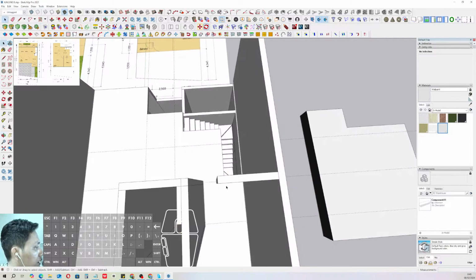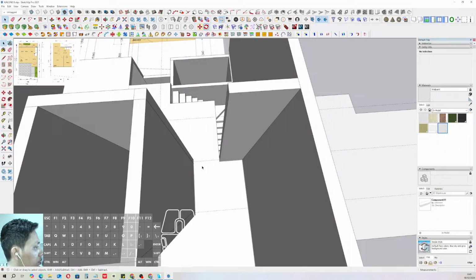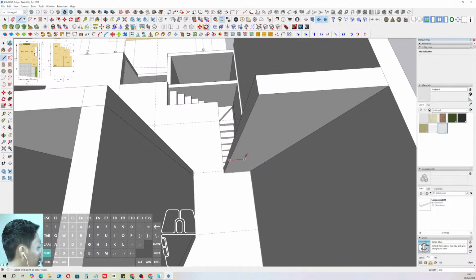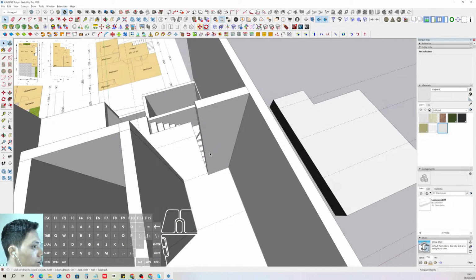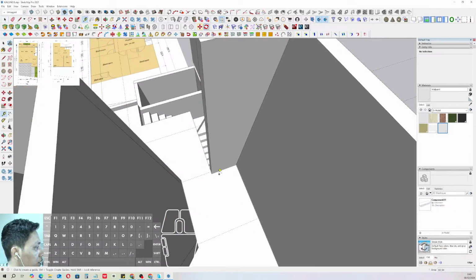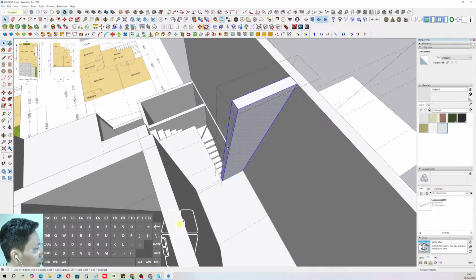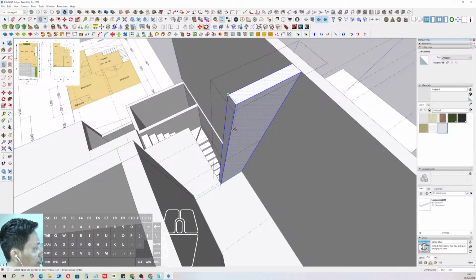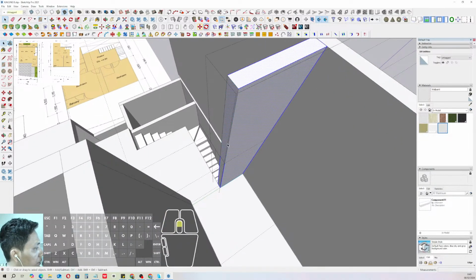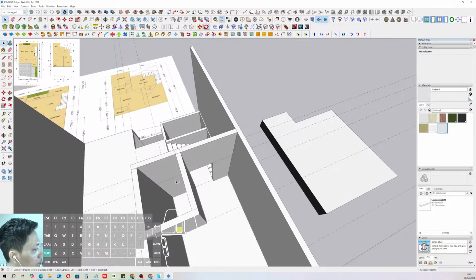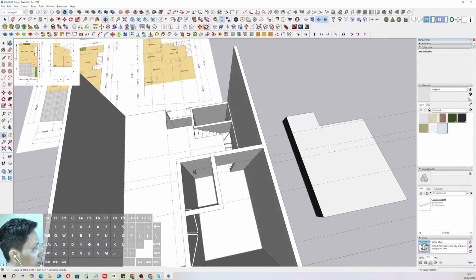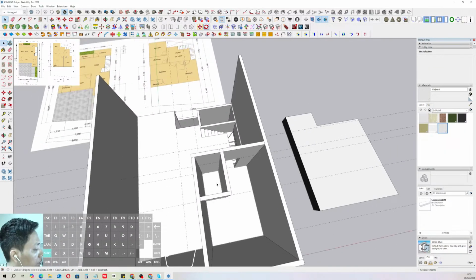Okay, and then we can put the door space in here. It's around 1 meter approximately. So we can give it a wall opening in here around 2.4 meter. Enter. Then we can triple click this wall and adjust the top opening to be the door opening. Anyway, this is the communal bathroom or the communal toilet, so we have to